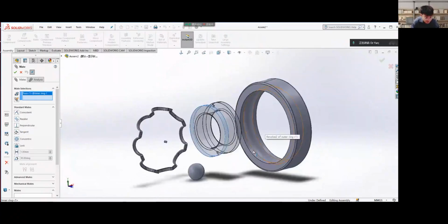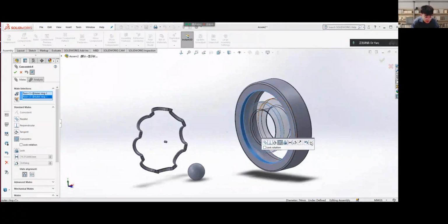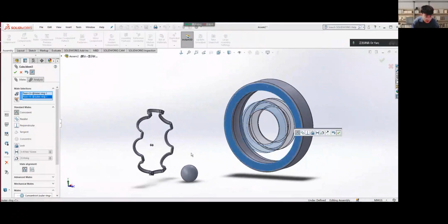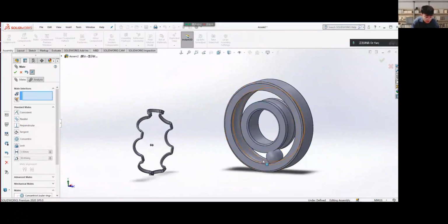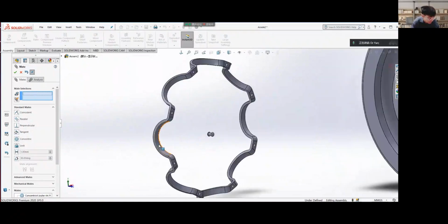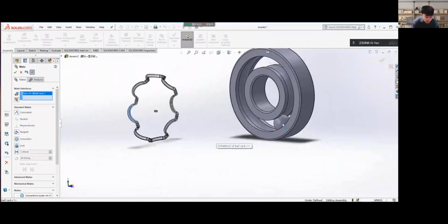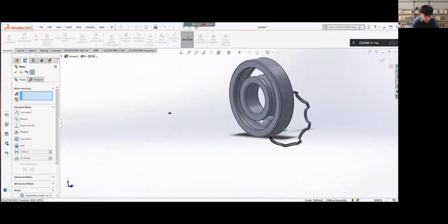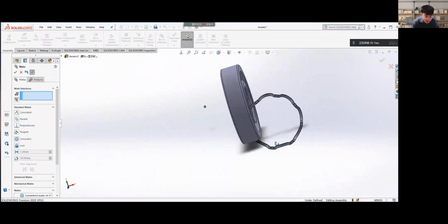For this time, the same thing right here to make them concentric, and this surface to this surface, go inside and move the bow inside of this, and make this bow to this surface tangent, and this surface to this surface tangent too. And this surface to the bow surface. All right, maybe some of you missed some problems at this time.